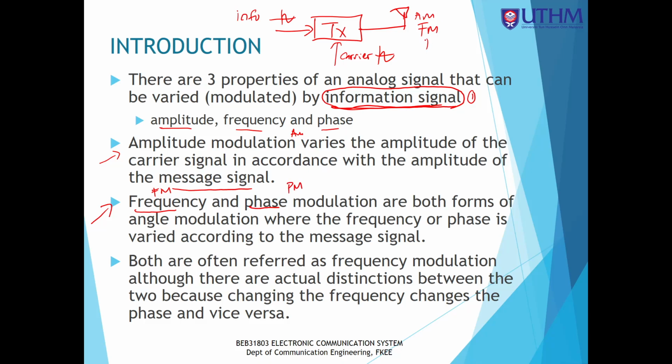And you will produce PM signal. And then what? Both are often referred to as frequency modulation, although there are actually distinct between the two, because changing the frequency changes the phase and vice versa. So both FM and PM are commonly referred to as FM in practical cases.